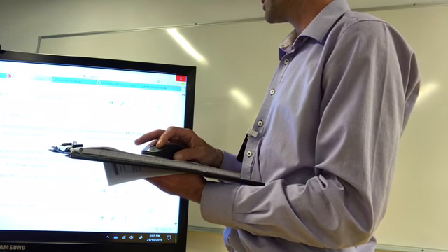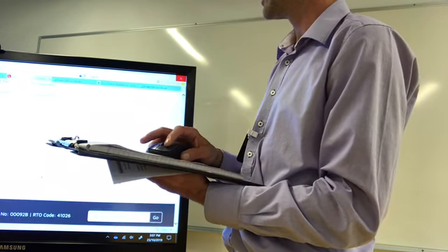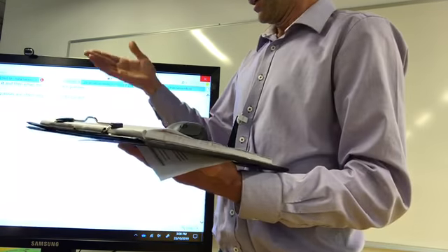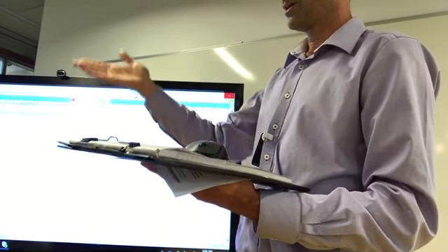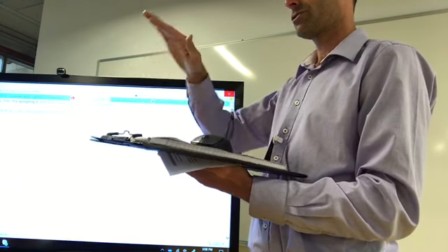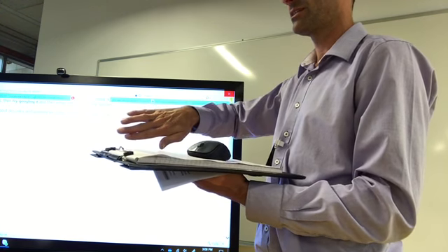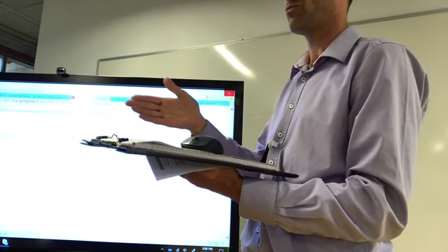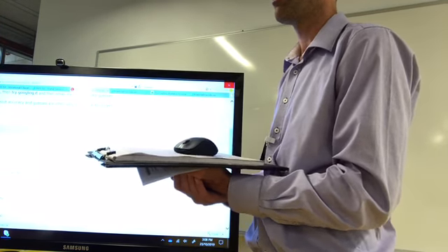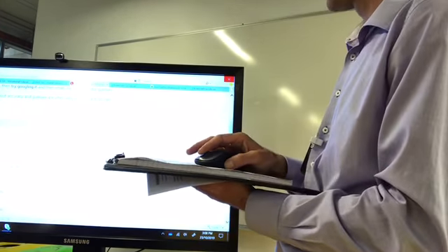I have not seen a detail that has a folded sheet metal flashing going directly on top of the EPDM membrane, and I think the reason is that you'd get wearing between the two, or the possibility of puncture of your softer membrane as a result.